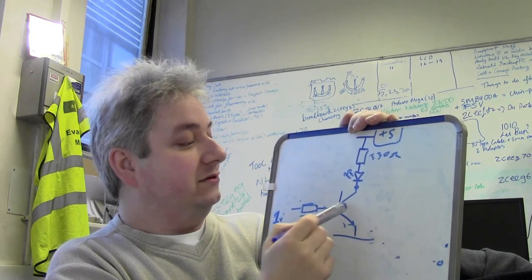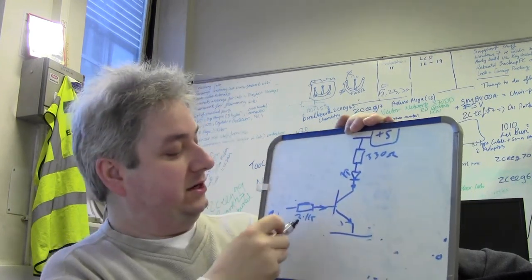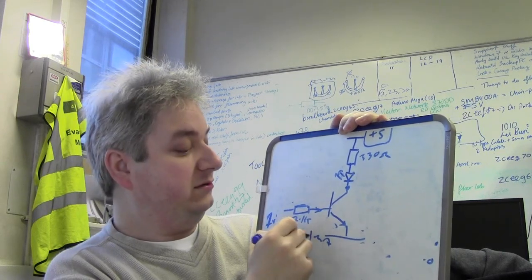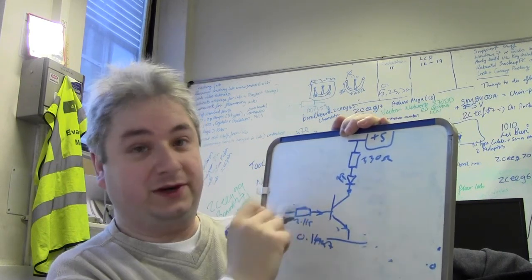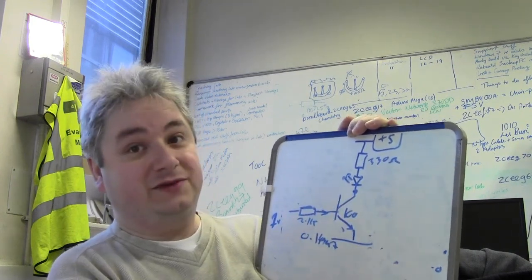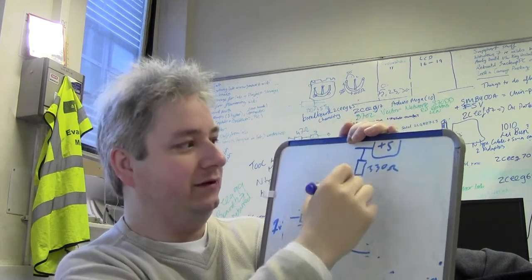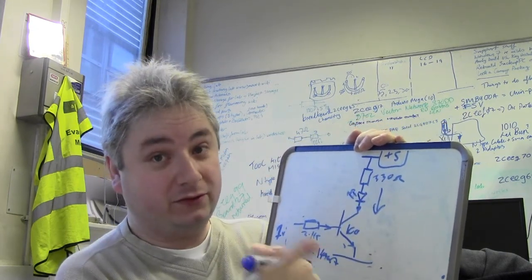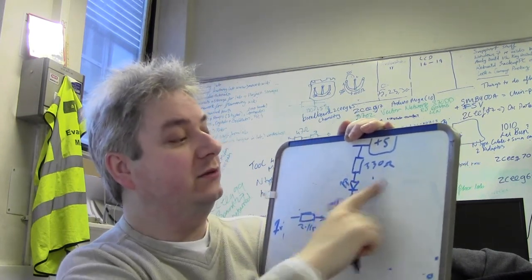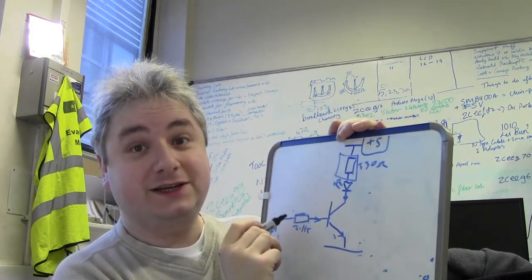If this gain goes up, and we've got 0.14 milliamps flowing in, and this was a gain of 100, we wouldn't have 10 milliamps flowing here. This will be 100 times greater. We'll have a ton more current flowing through here. But we don't have to worry about the gain increase because of this resistor.